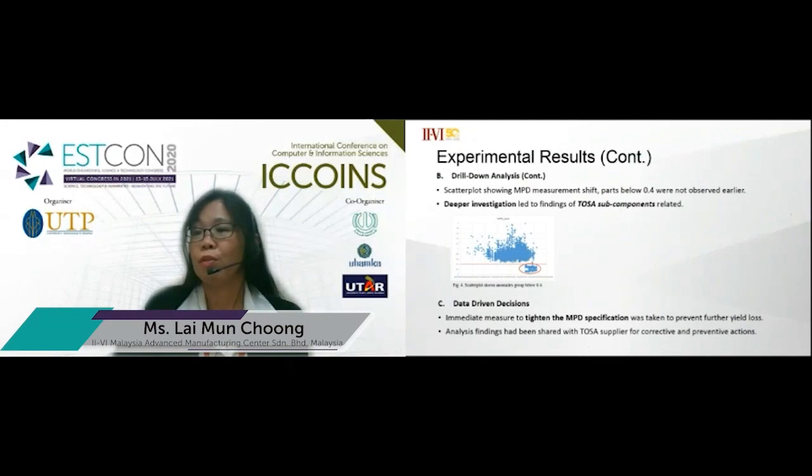A scatter plot shows that the MPD measurement has shifted. Parts below 0.4 were not observed earlier, and this brings to a deeper investigation that led to findings of TOSA subcomponents related. The data-driven decision that immediate measures to tighten the MPD specification was taken to prevent further yield loss. Analysis findings had been shared with TOSA supplier for corrective and preventive actions.